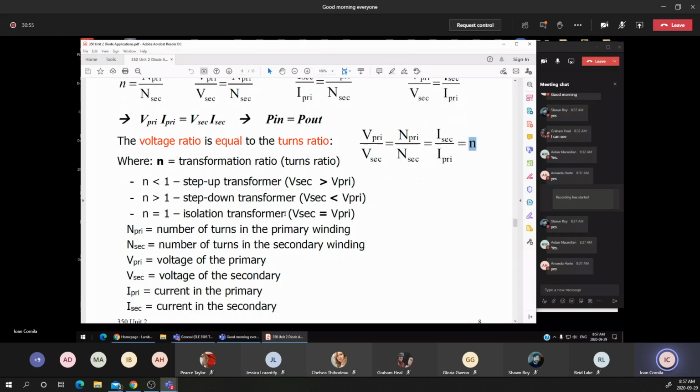If you remember, we used an isolation transformer and an autotransformer on the same equipment. But most of the time you will see an isolation type transformer used as a safety device in different applications. For example, I use an isolation transformer in the labs to prevent any electrical shocks for the students when they are touching those AC voltages.